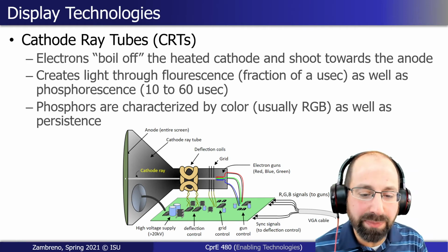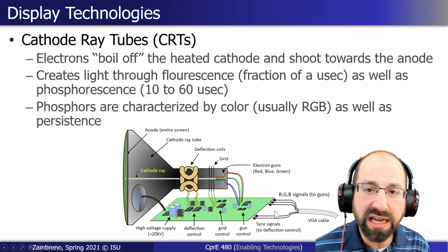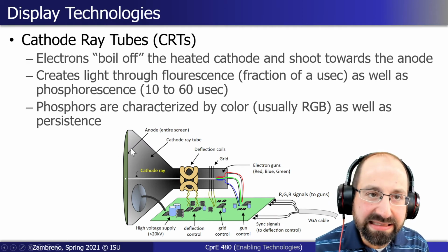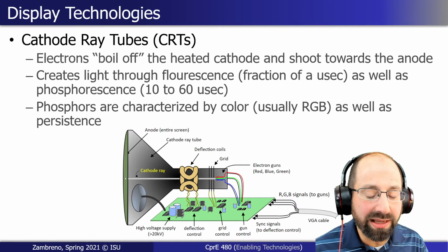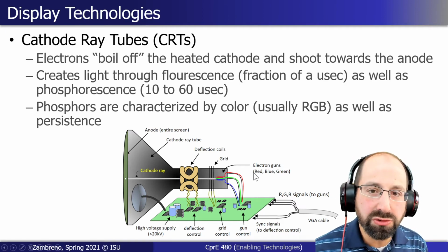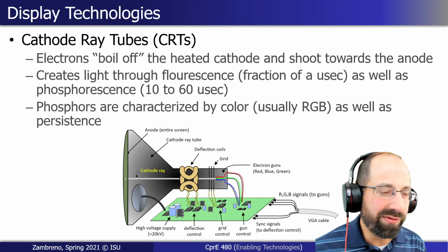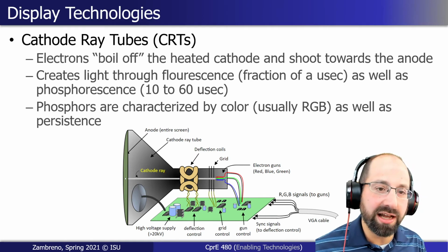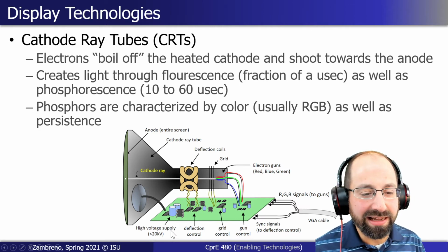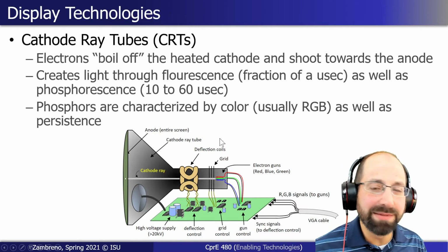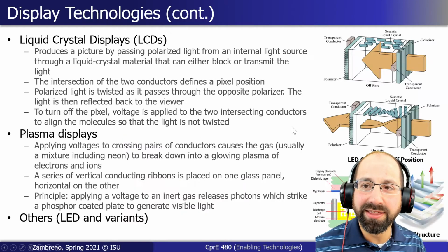And so a lot of what's happening in that circuitry is control logic that takes in the input signals, and we'll talk about the actual VGA signals that are coming in here. And as this thing is scanning its way through the system, that raster scan we were talking about is an actual physical process happening in this style of display. We have control circuitry that's modulating how bright, how many electrons are we firing off for the red, blue, and green of every individual equivalent of a pixel location that we have there. To do that properly requires a really high voltage display, which is why people say don't open up old CRT monitors unless you're sure you've discharged those capacitors properly, because they're fun and they're potentially lethal.